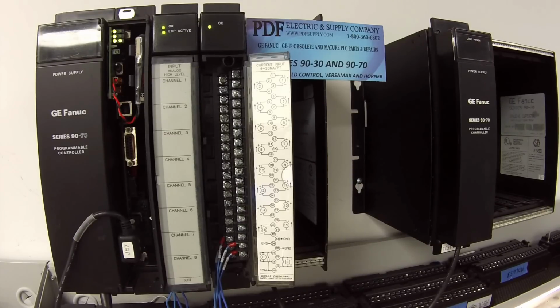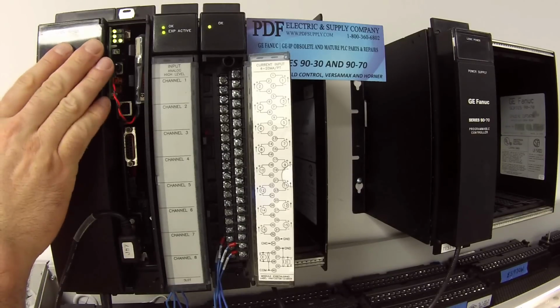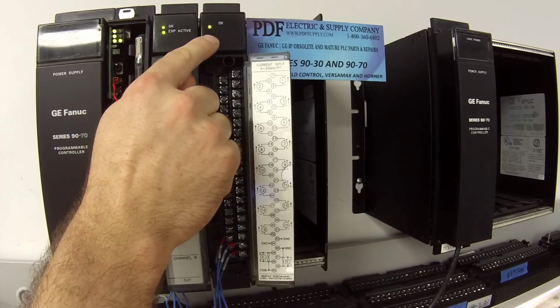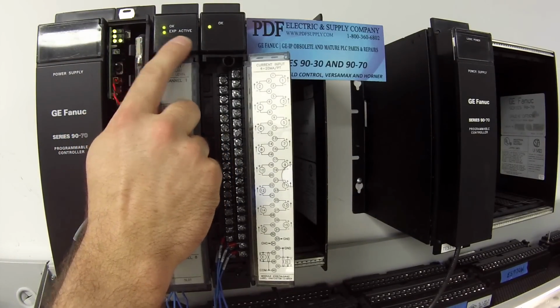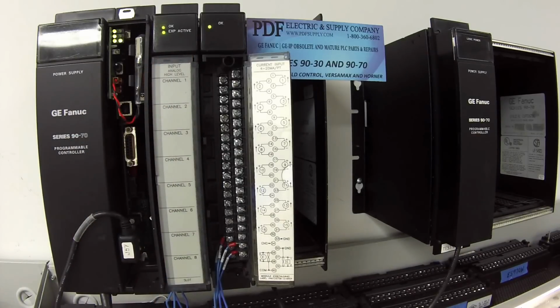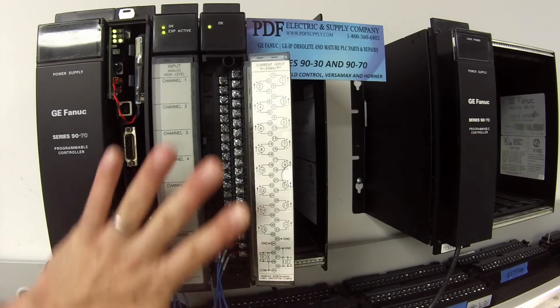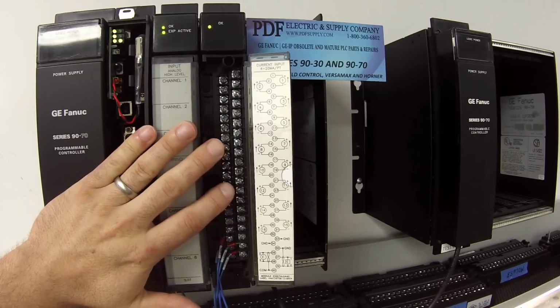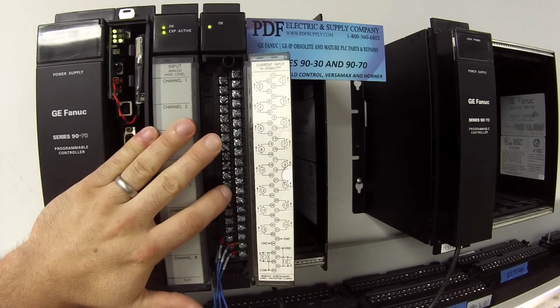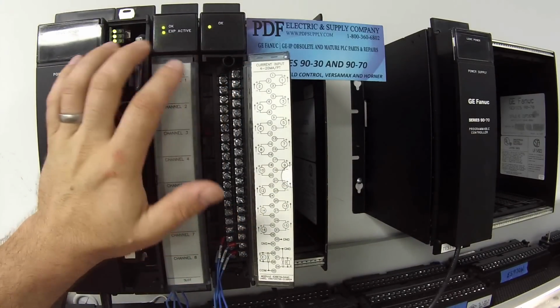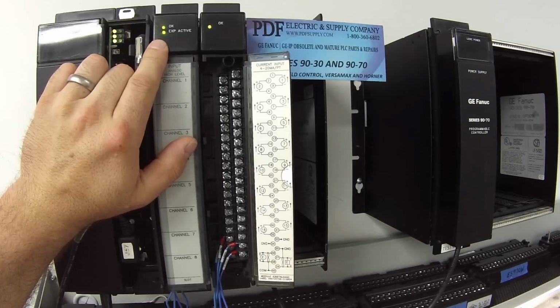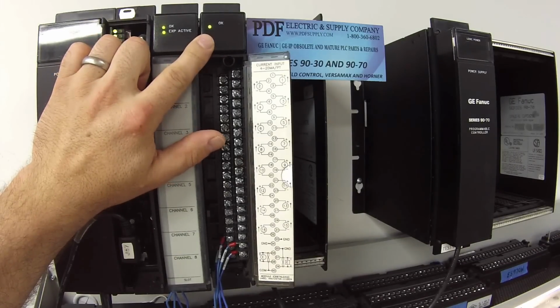The next thing is I have this already in run mode, and as you can see, my lights that are on, my OK lights are on both modules, and the expansion active is also on. A little troubleshooting tip for you. Occasionally, when you first set up these systems, I've seen more times than not that these lights won't always be in this configuration. What I usually see is that the expansion light is off, and again, this is when you initially set these up, and the OK light on the expansion module is blinking.